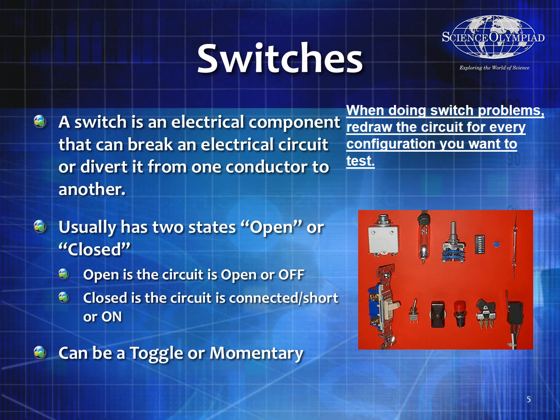So my recommendation is, when you do a switch problem, redraw the circuit for every configuration that you're going to test. In other words, it is a completely different circuit when the switches are in one position versus another.